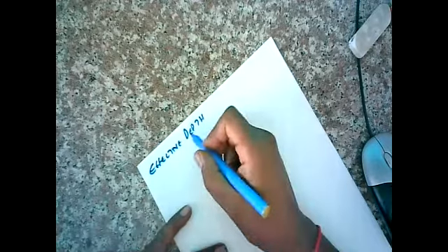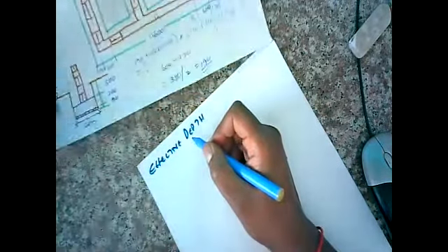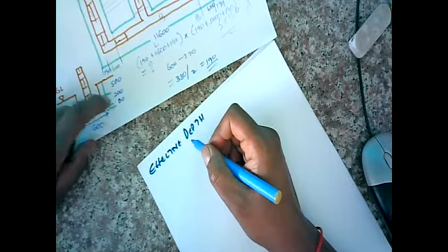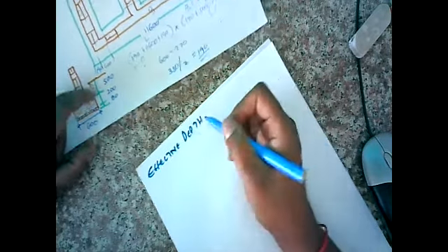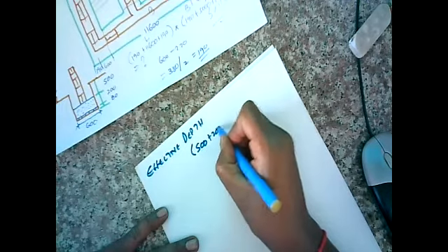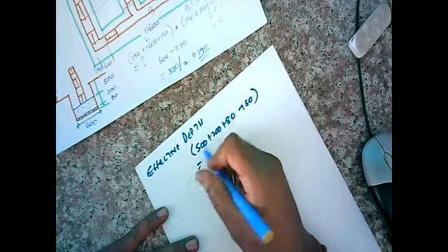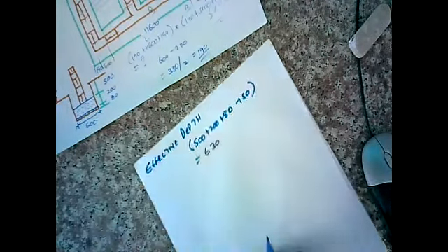What's our effective depth? There we go. 500 plus 200 plus 80. Remember the blinding. Don't forget the blinding. But we already removed topsoil. So effective depth is 500 plus 200 plus 80 minus 150, and we're getting a value of 630 millimeters as our effective depth.